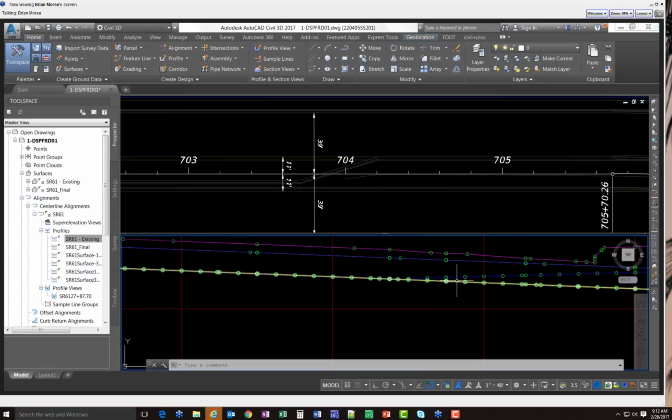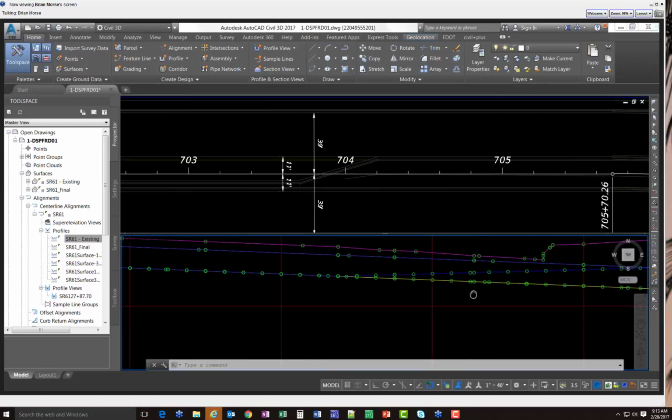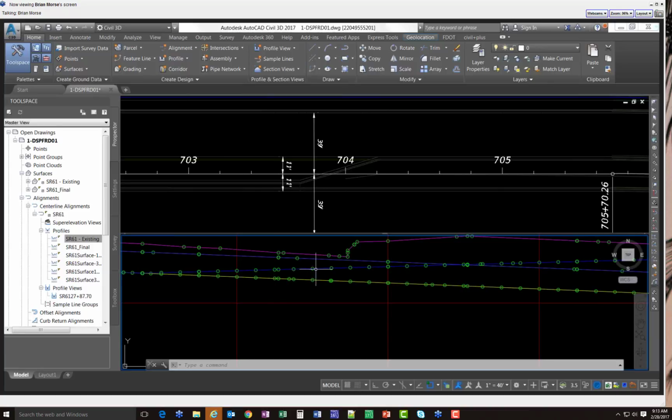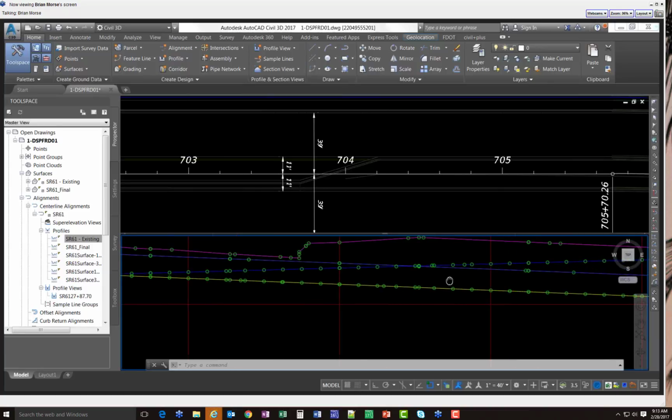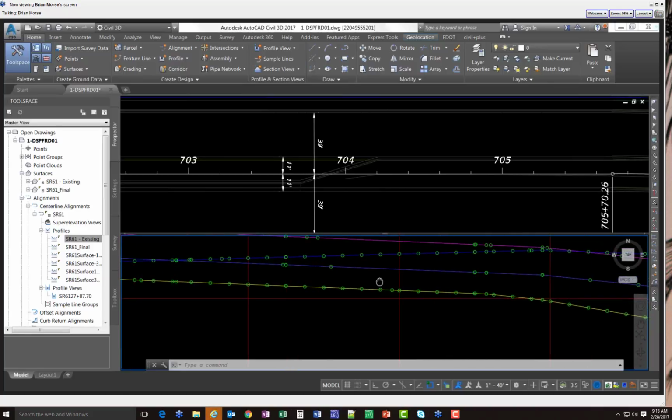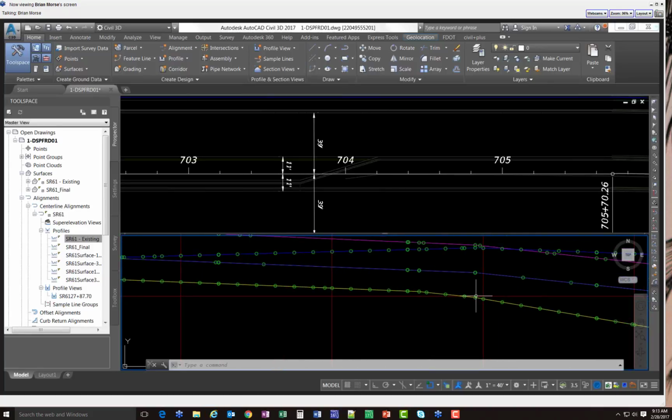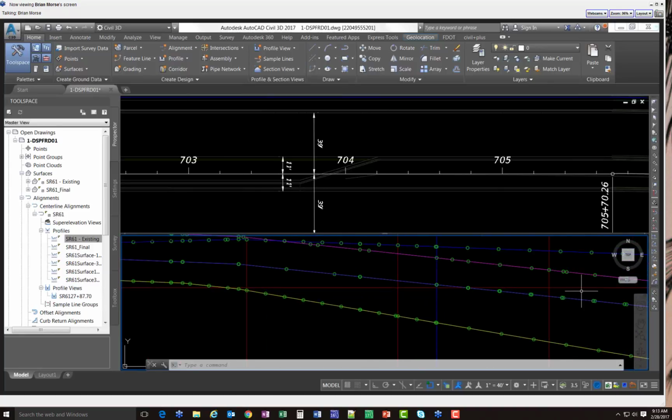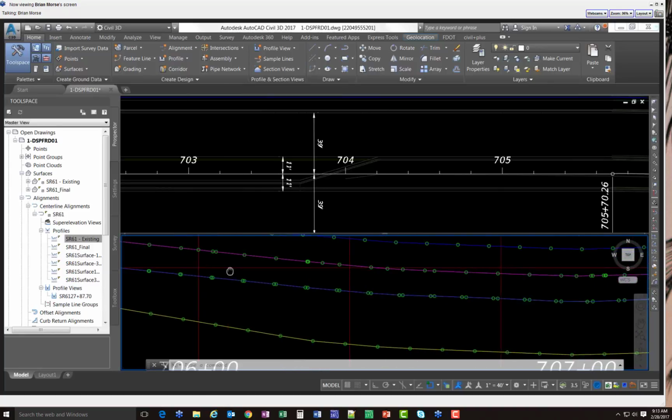Now, when you get to the outer profiles at the 39 feet, then you can see they start to look like super elevation profiles. You know, you've got the lane line that whips out there, and then you've got like a constant cross slope right here, 2%, and then it goes into full super, and look at that, it's just fabulous.